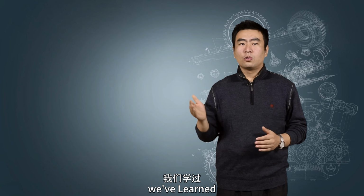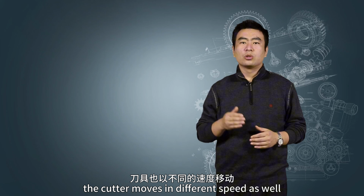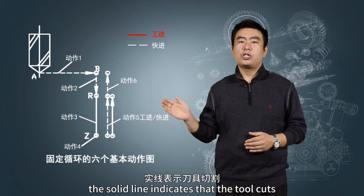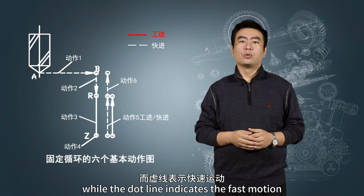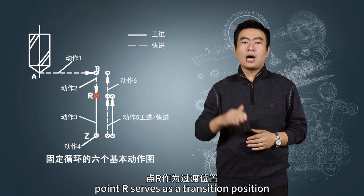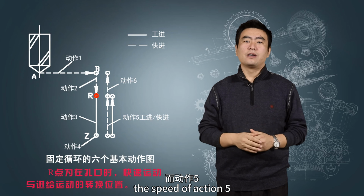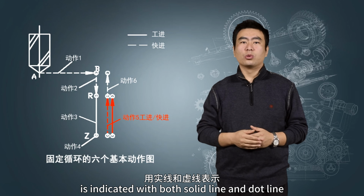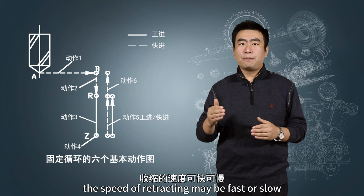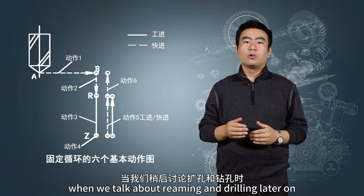In the animation, we've learned the general procedure of hole processing in a fixed loop. And in different actions, the cutter moves at different speeds as well. For example, the solid line indicates that the tool cuts at the speed of G01, while the dotted line indicates fast motion at the speed of G00. Point R serves as a transition position at the top of the hole from fast motion to feed motion. The speed of action 5 is indicated with both solid line and dotted line. It means that in the processing of different holes, the speed of retracting may be fast or slow, which will be specifically introduced when we talk about reaming and drilling later on.